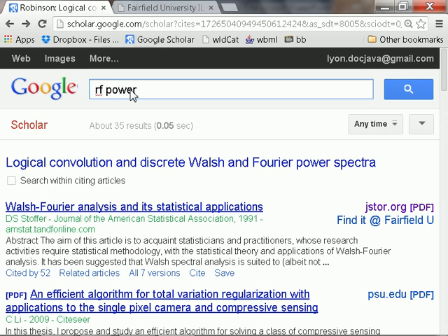Well, if you're talking about low power energy harvesting, you can harvest from solar, from thermal, and from vibration. And so for low power energy harvesting, it's very good if you're in a place with high excess energy. Like, for example, in a helicopter, it's vibrating all the time. So if you have a piezoelectric energy harvesting system on an RFID tag type processor, you can make a distributed sensor system.